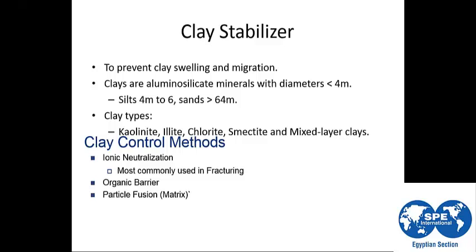So if your fracture fluid resulted in clay swelling, where will this clay swell? It will swell inside your pore spaces. This means that your pore spaces will be occupied by swelled clay, instead of being clear to pass the hydrocarbon through. So it is a very critical point to keep the pore spaces clean and to avoid any clay swelling.